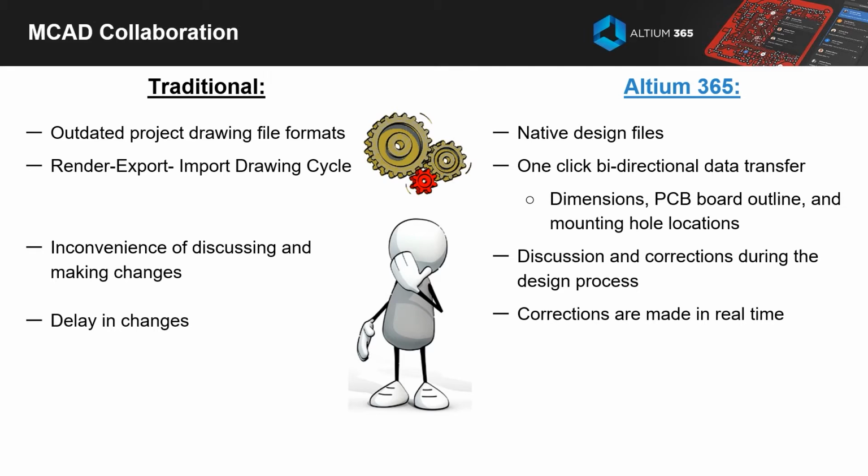ECAD collaboration with mechanical engineers requires some special attention. The designer receives input data with restrictions on the location of design elements and instructions for the exact location of holes and connectors. Often it's a drawing rendered in another program that must be exported and then imported into Altium Designer. As a result, the whole drawing must be adapted accordingly to necessary layers and PCB shape.